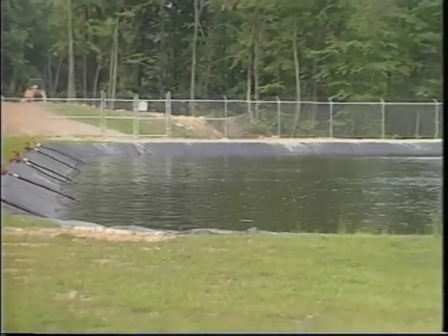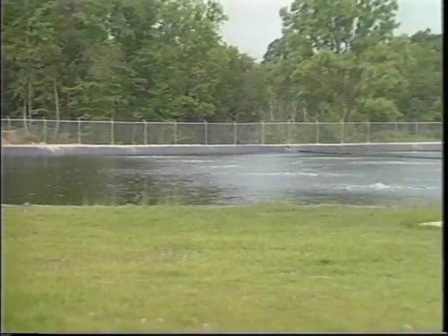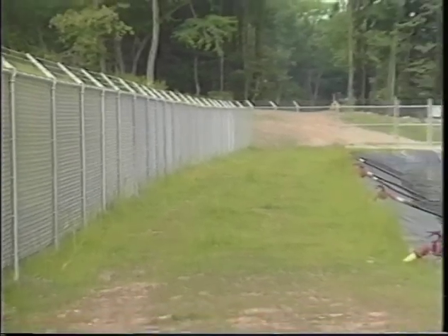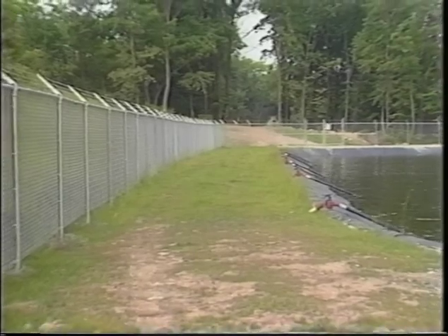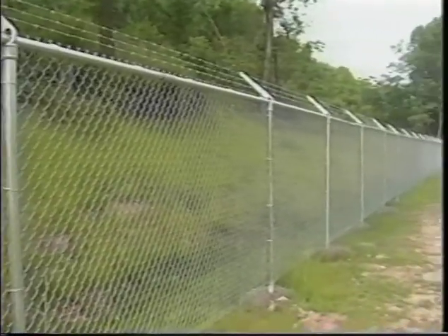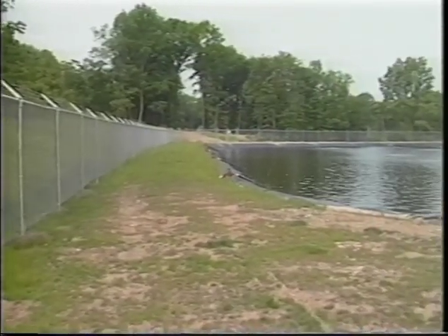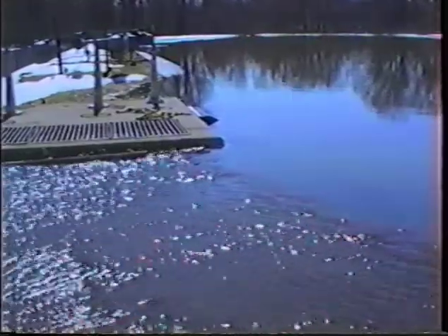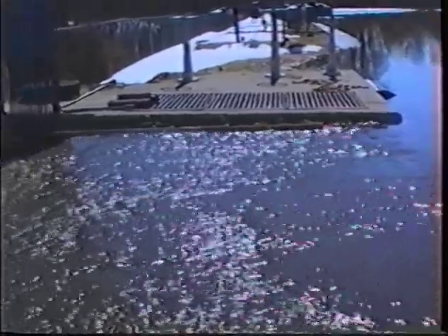Monitoring the depth of the sludge blanket in the lagoon is necessary to help determine the rate of accumulation. Proper maintenance of lagoon property and embankments is a must. Keeping weeds under control near the water's edge is necessary to prevent the breeding of mosquitoes. Burrowing animals should be removed from the embankment area, as they can damage the integrity of the embankment. The operator should repair any gullies or washouts that occur in a lagoon embankment. Overflowing can place the lagoon embankment in danger as well.